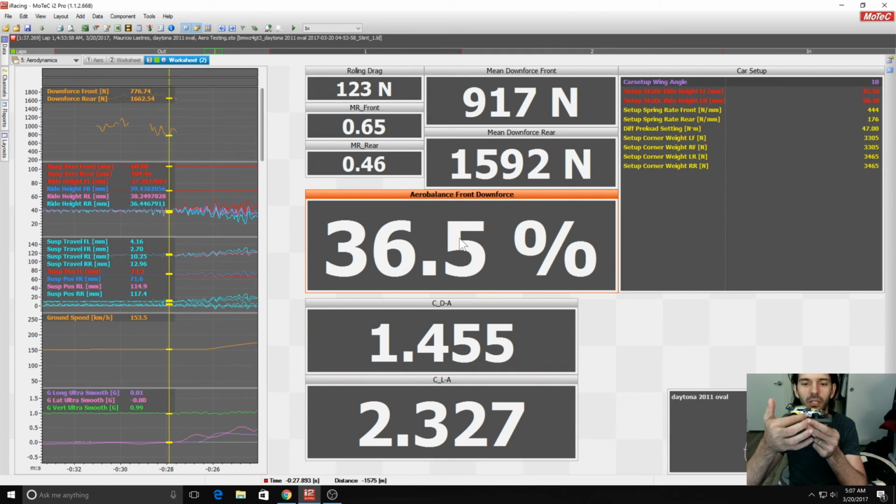Once the car is set up, it's set in that location, and that's where the weight transfer happens from. Every time that you're turning left and right, how the car moves is all dependent on the location of the center of gravity. But the center of pressure is obviously only acting at high speeds where the aerodynamics come into play, and that we shift with the wings.